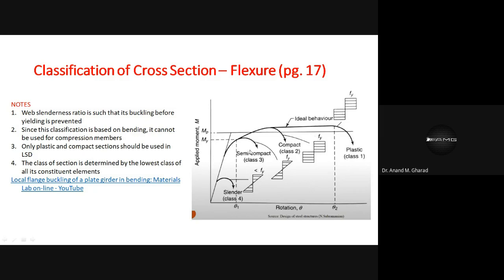We should not think of semi-compact or slender sections, right? We will slowly see this whenever we solve numericals. If for some reason our design comes in this range, then we are supposed to redesign it and go to compact or plastic. That we will see how to do.